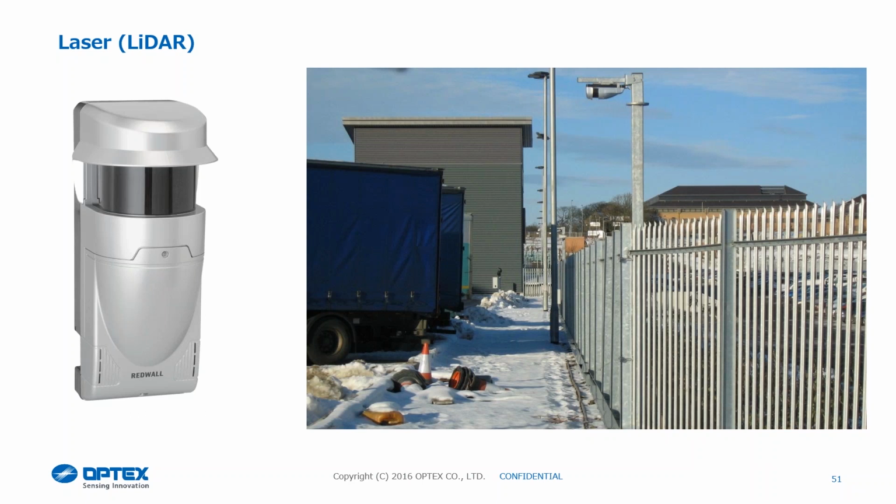The other thing to consider is active beams. If you did look to put active beams on there, the fence line is a potential climbing aid, so we're going to have to keep 1.5 to 2 meters back from that fence line. The problem on that site is, as you can see, there are vehicles on the left-hand side. At best, those vehicles are going to reverse further back than that and block the zone, so you're not going to be able to set that system at night time. At worst, they're going to reverse into the active beam tower and knock it over, so you're going to have to go back and refit it and replace it.